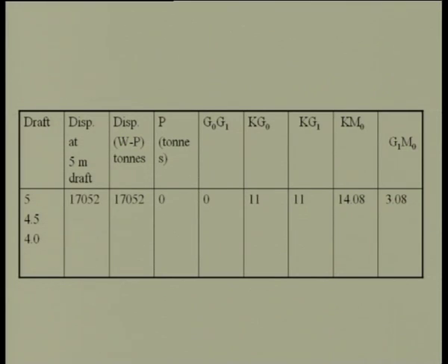Kg for instance does not depend upon the draft in that sense, because it is the weight of the ship, g does not change, but those are some of the advantages of the second method. But km will change, depending on the draft m will be at some point, and when you change the draft m will shift, it will come down or go up. Actually here I will draw this figure, it looks like this.